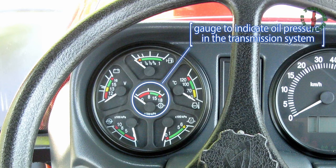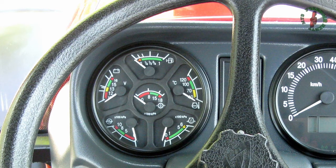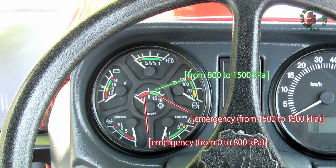Gauge to indicate oil pressure in the transmission system indicates oil pressure in the hydraulic system of friction clutches control in the tractor transmission. The scale of oil pressure has 3 zones, from 800 to 1500 kilopascals, and 2 emergency zones.